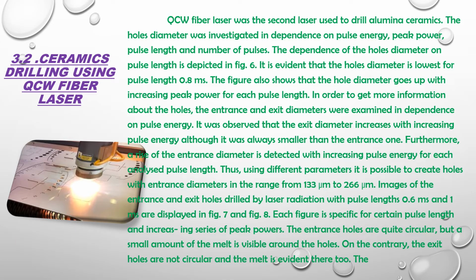Ceramic drilling using QCW fiber laser. The QCW fiber laser was the second laser used to drill alumina ceramics. The hole diameter was investigated in dependence on pulse energy, peak power, pulse length, and number of pulses.